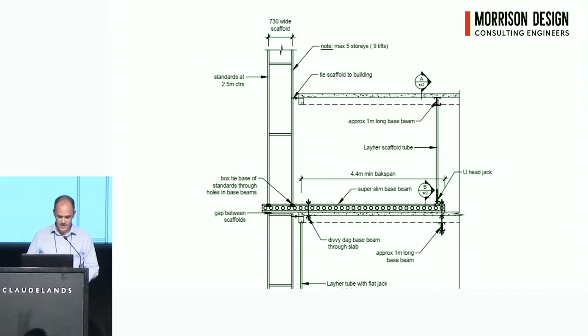As well as that, through that section there, we've got diagonal members running within the scaffold depth, so that if for whatever reason something did happen to one of these cantilevers, load could be shared out to the adjacent cantilevers to prevent anything catastrophic.